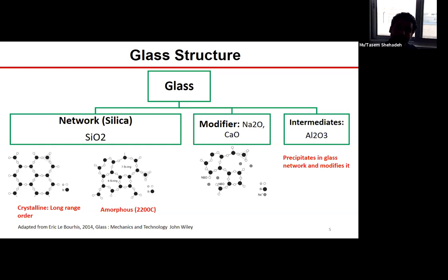In addition to that, maybe adding certain oxides during the processing of the glass, during the manufacturing process, such as lithium oxide, can help in removing some of the cracks, or maybe it can inhibit the formation of these cracks, or at least it can reduce or decrease their size. As for the range of the glass transition temperature, it depends on the composition, but I think it's in the order of 400 degrees, if I'm not mistaken. It's within that range of temperature.